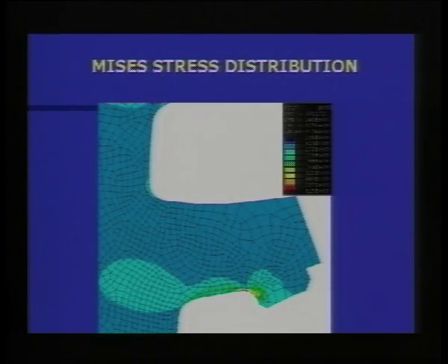For example, whatever stress value I have in this particular slide, I will straight away compare it with the yield strength of the material. It is about 37 kgf per mm squared, or around 370 Newton per mm squared. I will straight away compare whatever value I am getting there to the yield strength of the material I have obtained from my uniaxial test.